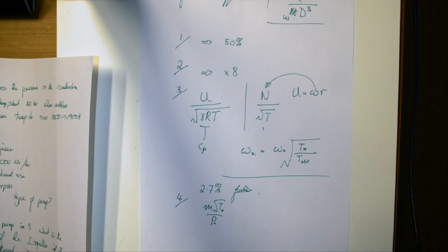So the experiment we're talking about is you've got an engine running, it's at steady conditions, and suddenly you put in more fuel. The transient that occurs has a constant value of this group, m root T upon P. That will not change. So we can calculate the change in the pressure just by knowing the change in the temperature.